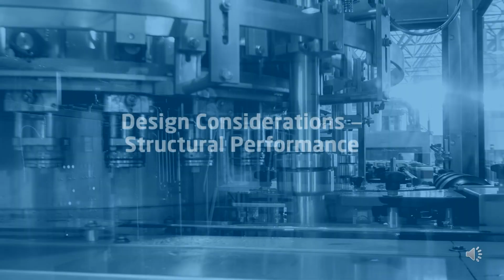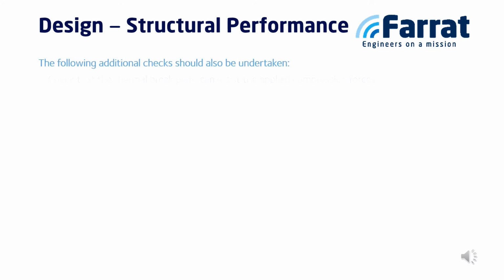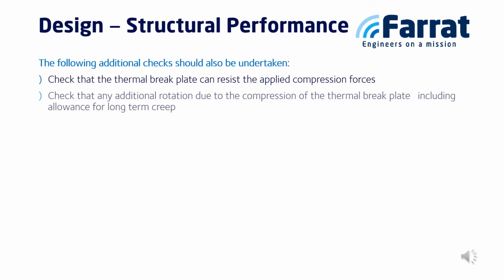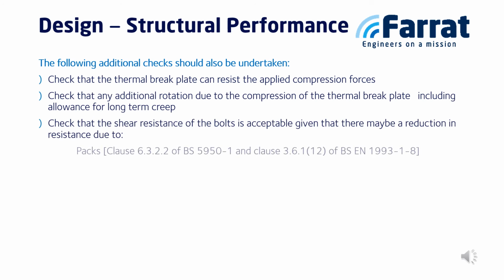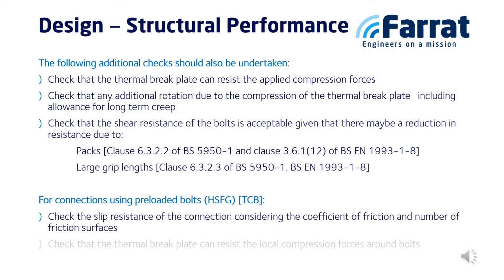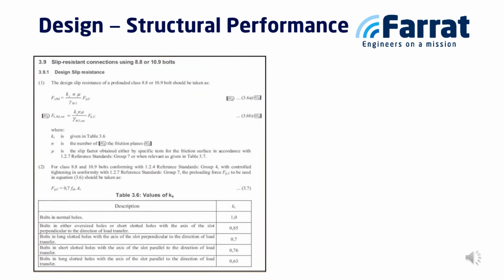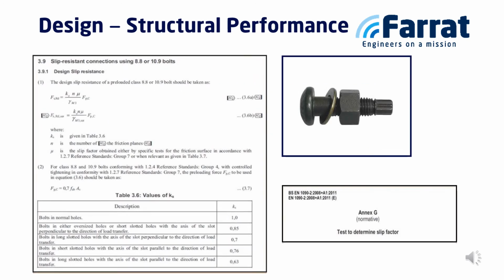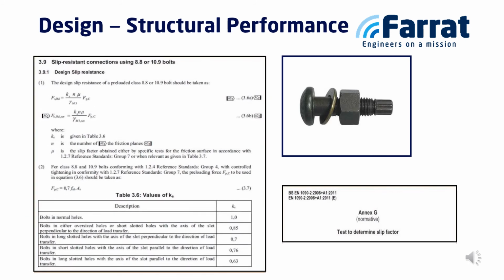Another critical design consideration is the structural performance. When designing structural connections with solid-state structural thermal breaks, the following additional checks should be undertaken to ensure correct performance. Here is a checklist for thermal breaks that require a HSFG bolt, predominantly a requirement in the US or the UAE following US design principles, but becoming more relevant in buildings with external skeleton structures.